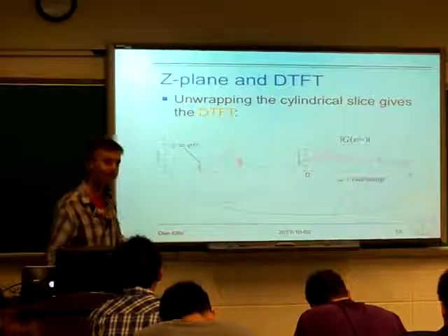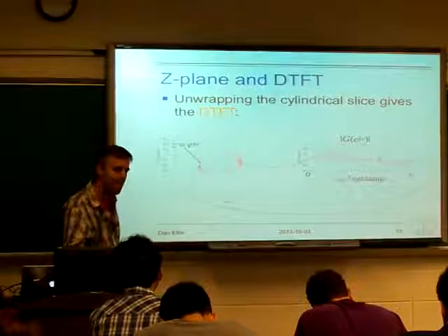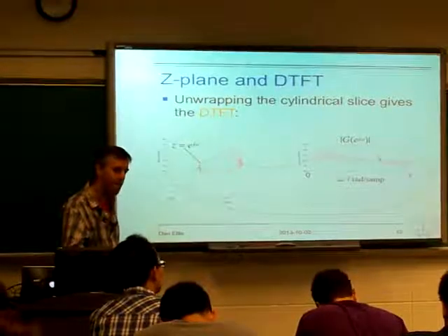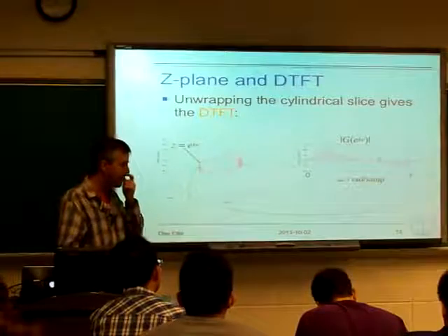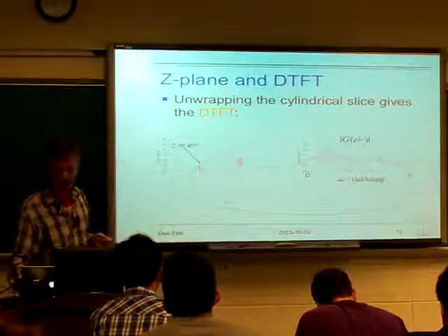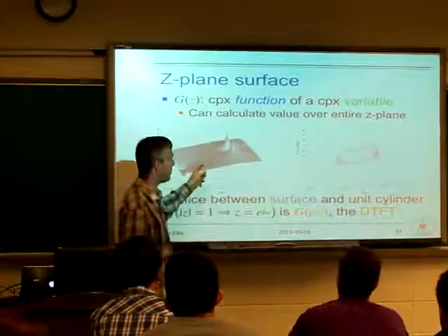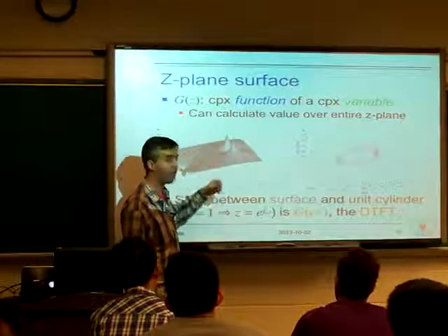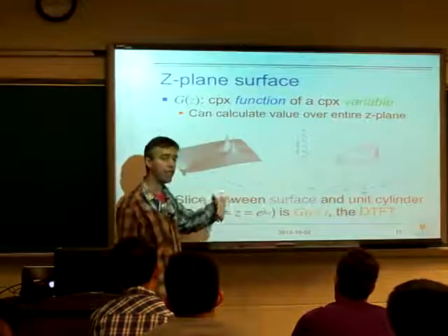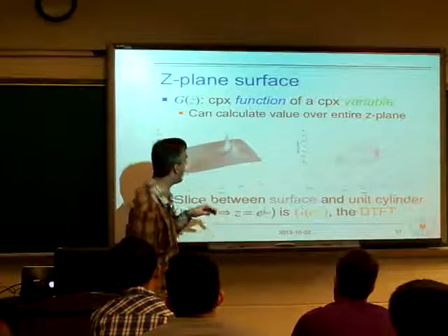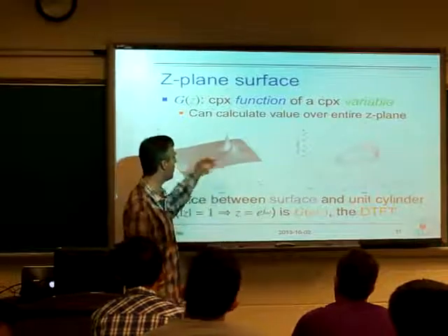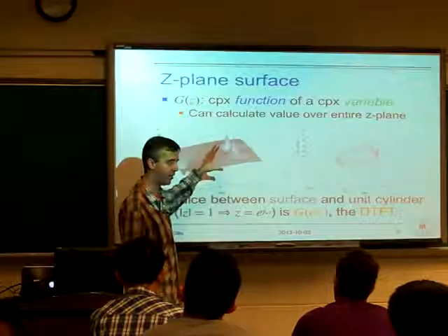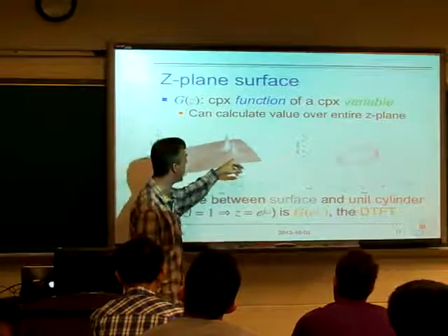Yeah. So basically, this correlation between Z transform and the FT. So this is basically done only in the region of convergence. Right. So that's a good point. Thank you. So here, see what I've done here. I've plotted the x of z, the closed form expression for all values of z, and the region of convergence has been forgotten. Right? I've just said there's no actual sequence that has a z transform that can take on this form. I've stated that. I haven't proved it, but it's true.